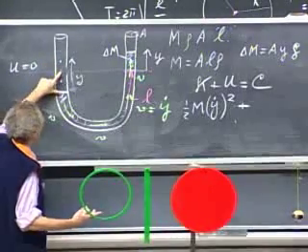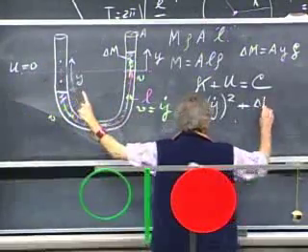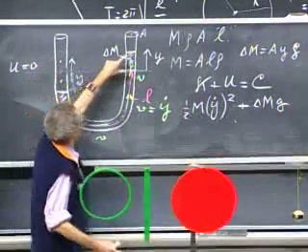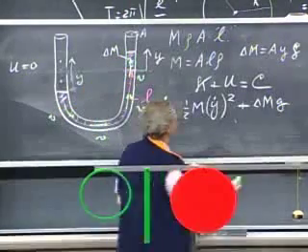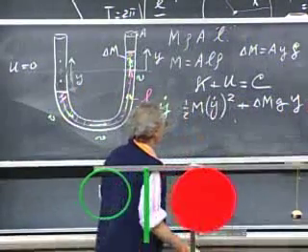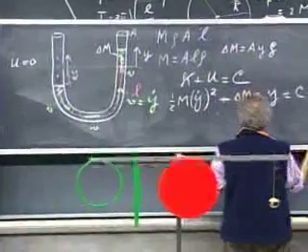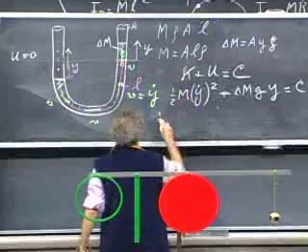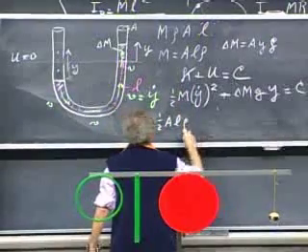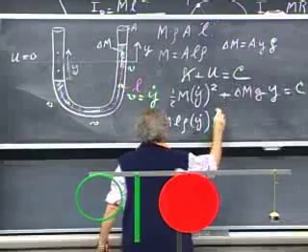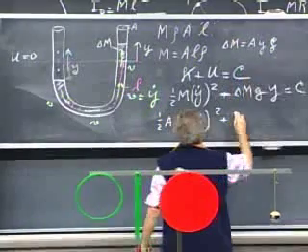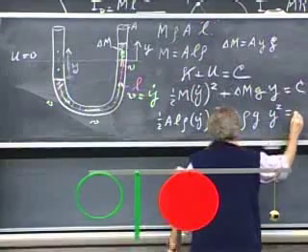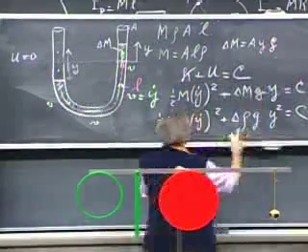Remember, mgh is the increase in potential energy. And so I move an amount of mass, delta m, over a distance y. I bring it here, but that makes no difference, of course. And so this is the total energy, and this is now a constant. So I'm going to substitute in there the A, L, and rho, so I get 1/2 A L rho velocity squared plus A rho g y squared equals a constant, because I have a y here and I have a y there.